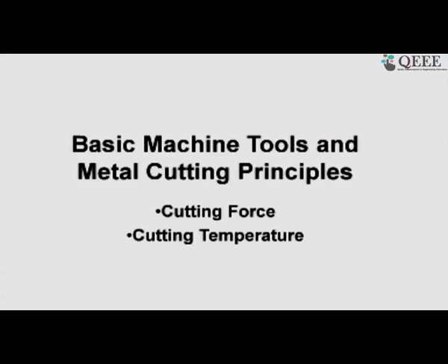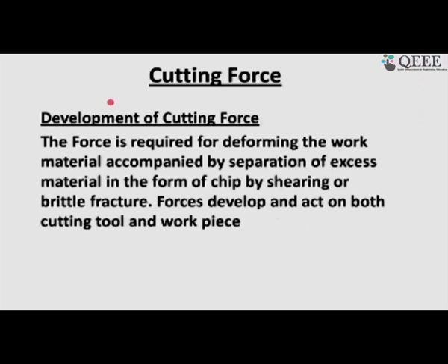If we go to the next slide, this is a small description of how this cutting force is developed. This force is required for deforming the work material which is ahead of the cutting tool, and the force develops because of the resistance offered by the work material. So, it is the strength of the material that makes this growth or development of the cutting force.